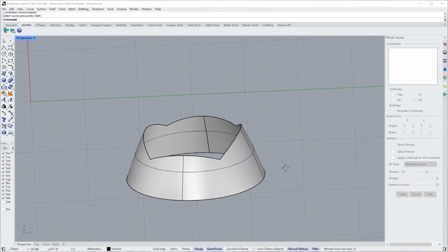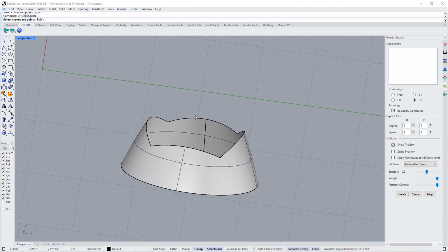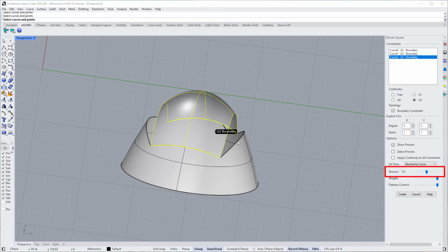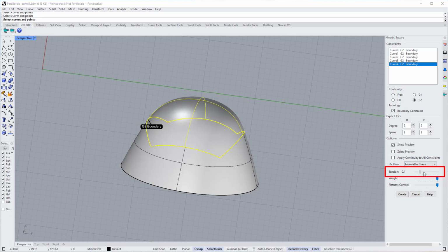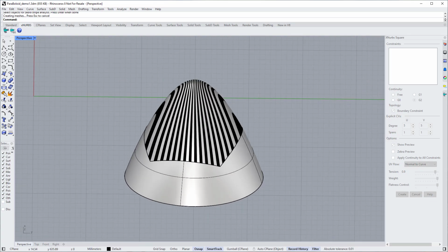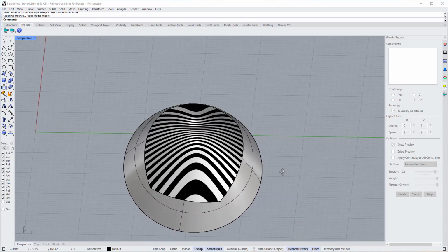Version 7 adds a tension option for Square and xNURBS command. When specifying G1 or G2 for an edge, it controls the influence of the edge. You can use it to adjust the shape of the generated surface or the surface bulge. xNURBS is super fast and all regenerations are done in real time. Generally, you should use the default setting for the tension slider because the default tension setting is a reasonable or optimized value. Only change it if the default tension does not generate the desired surface.